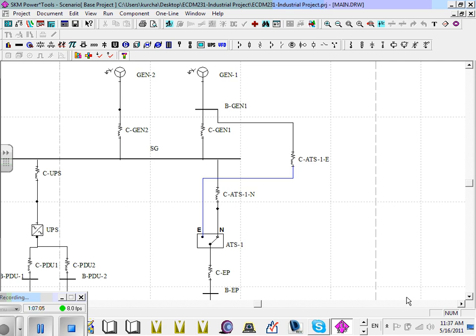If you make a mistake on one, so I need two cables, no problem. Now you need to drag that one and put it here. Are you guys all there? Just hook the one generator up. That's how we normally do it, guys. The emergency panels are connected directly to one gen. So when we fire the gen, we first energize the emergency panel through the auto transfer switch, and then we pick up the whole load of the building.